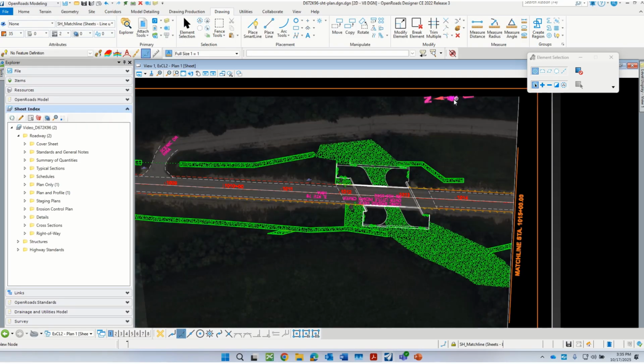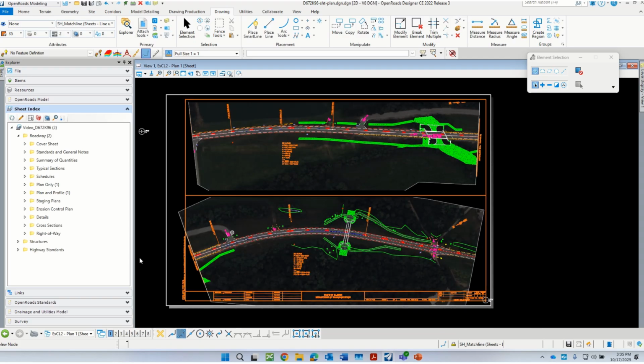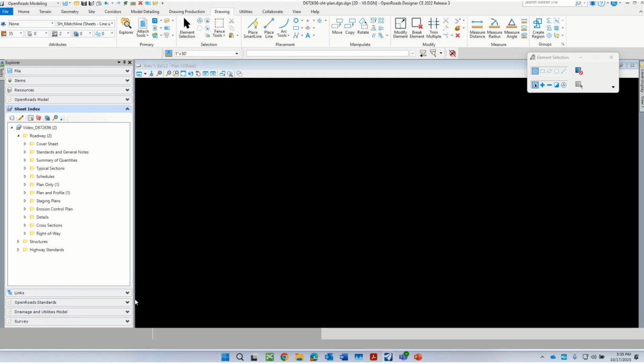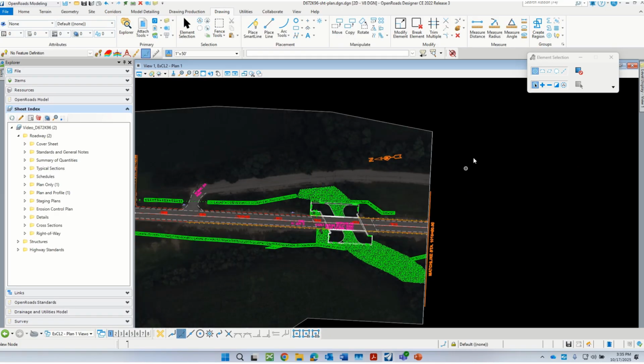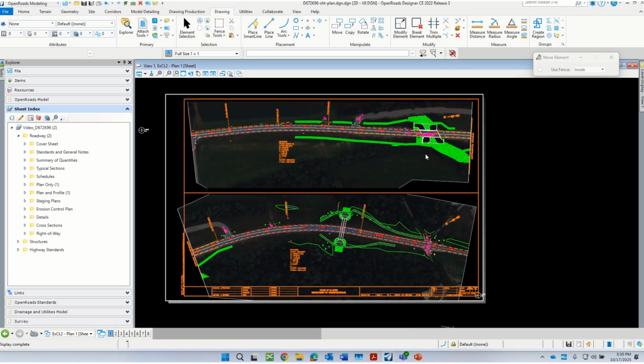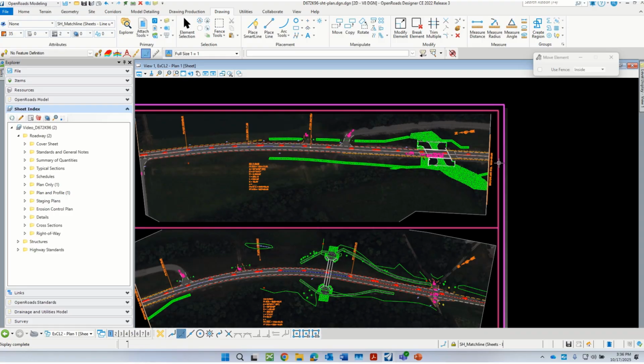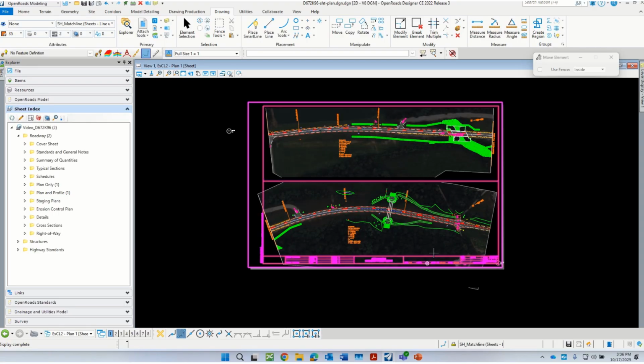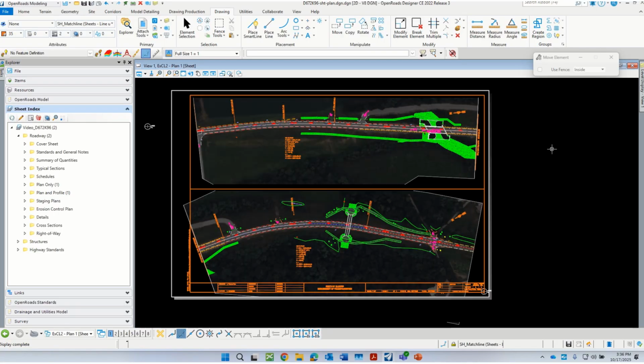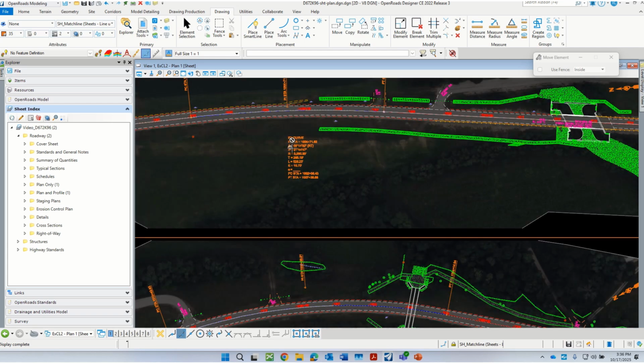Yeah, I see how I'm clipping off that north arrow a little bit. So in that case, I want to go to the drawing view, number 1, and I can grab that north arrow, which again is part of that annotation group. I can pull it down, and then when I go back into the Sheets model, I'll notice that it's where I want it to be. Oh, let's see, what else could we do?